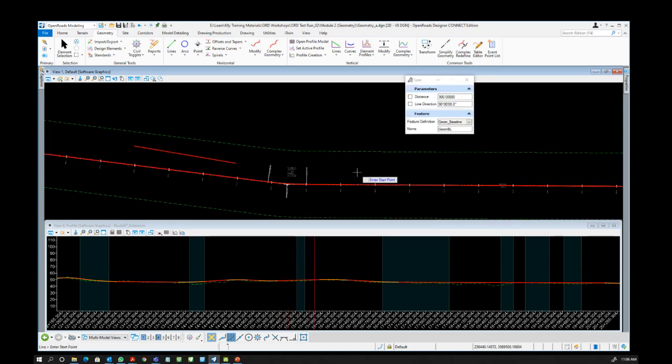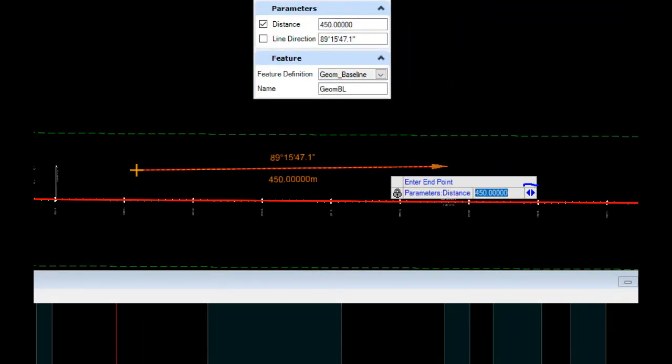So if I want another line in here, I click here. Same thing. I have a distance parameter of maybe 450. Enter that. I want an angle of, let's say, 85, and so on. Sorry, I click 450. Then to go to the next option, press the left or right arrow key. So every time, you're seeing this left or right arrow key.